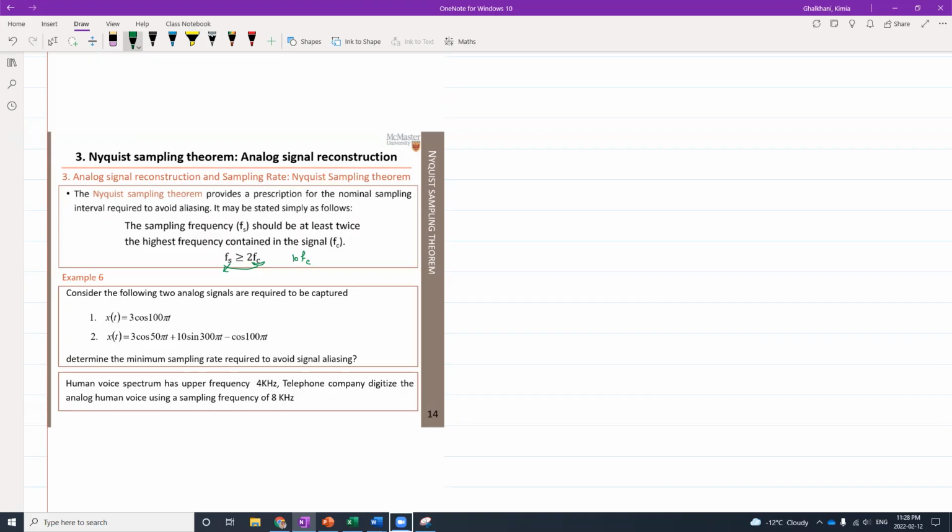We already said we should consider the number of inputs, and the resolution, for example 8 bits or maybe 16 bits. And now the other challenge is considering the frequency. We have to consider the frequency of the analog to digital converter. So if the Nyquist rate is about 1 kilohertz, it is good for real application.